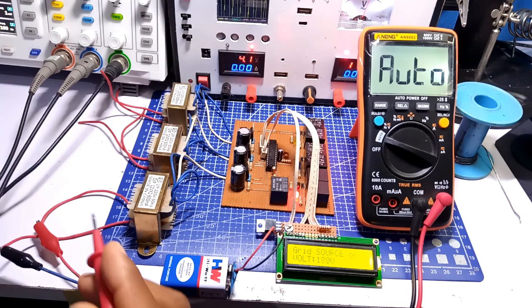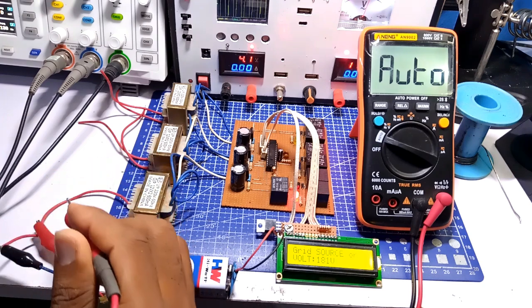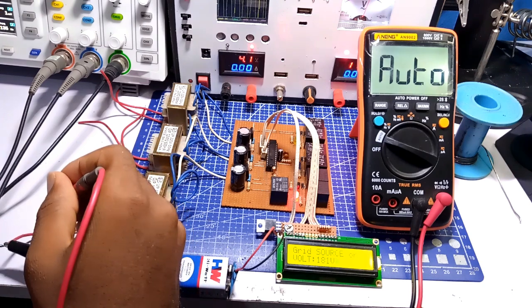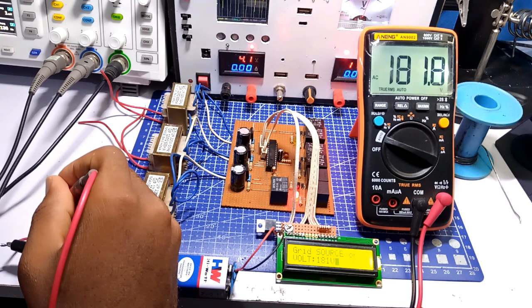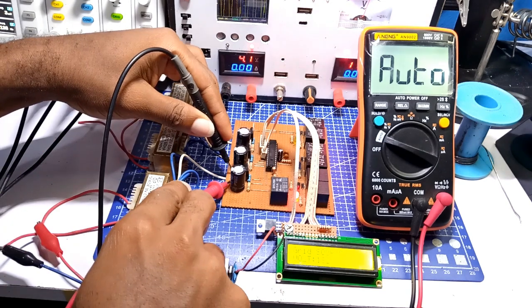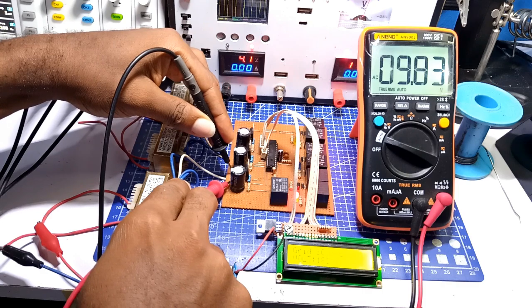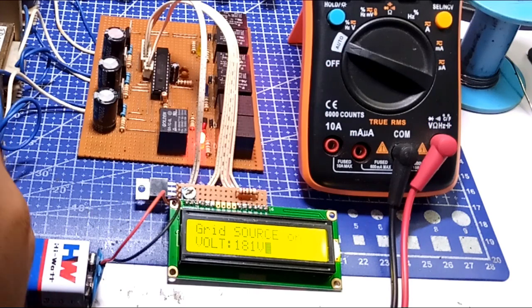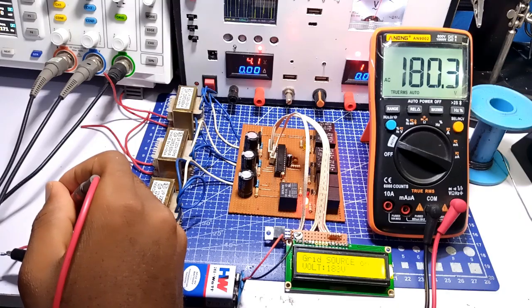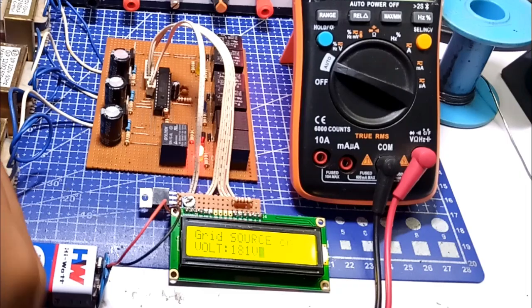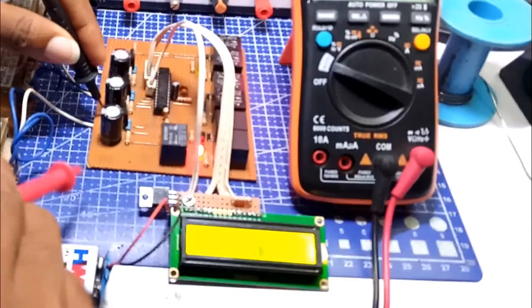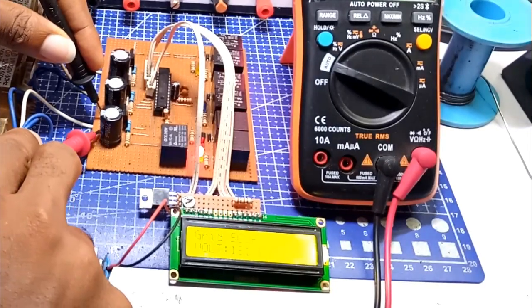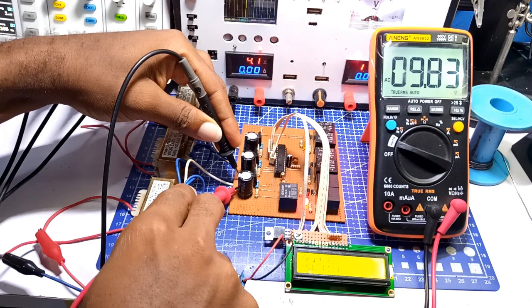If I take this reading while powering the relay and the microcontroller, my values will be affected. I have 180 volts as my AC input and 9.83 volts as my AC output voltage, instead of 10.82 or thereabout. Even though I'm running my lab with my generator, whose output voltage is not so stable, this calculation shows that it's not good to take your reading while the components are powered. As such, it's best to remove the transformer entirely from the circuit and have it well isolated while taking your reading.